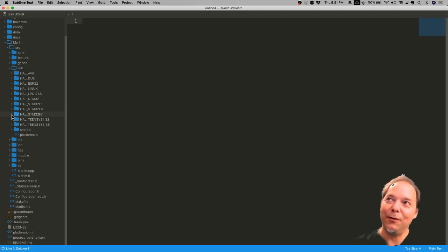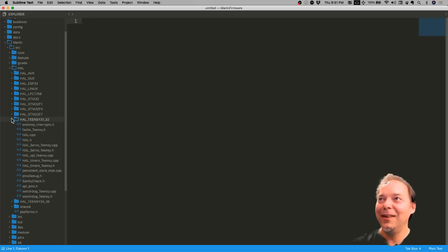So you can build for different boards based on just STM32. You could build maybe for all the boards with that one. But if you had an F7, you would maybe choose to use this instead and get perhaps better performance or different features and options in terms of timers and things like that. It all depends on the core and how it's built. They all have something like an Arduino type interface for the most part, and so we're able to just include something called Arduino and get most of the functions we need. But there have been cases where things are weirdly different, and you have to adapt to that. Most of the time, though, they are very much the same.